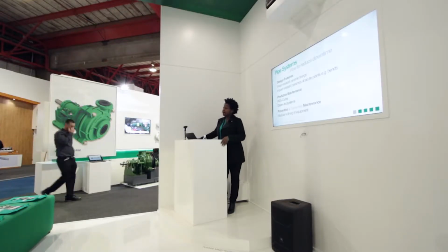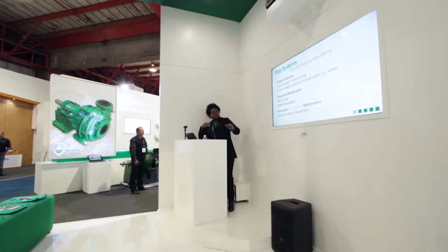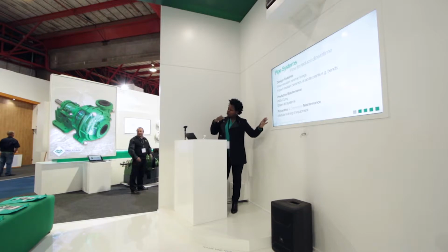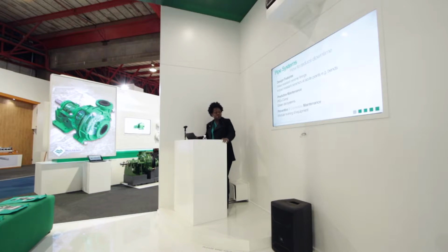We also have what's called the green dot system. This system works in a similar way, but it's more of a physical system. As the lining in the pipe is being worn off, the green dot, which is also a ceramic, is also being worn off until it gets to a point where it gets red, because it has a red ceramic underlying the green ceramic. When it gets to that point, you know that things are not right. You have to do the maintenance. And we have, like I said, the modular relining of equipment.